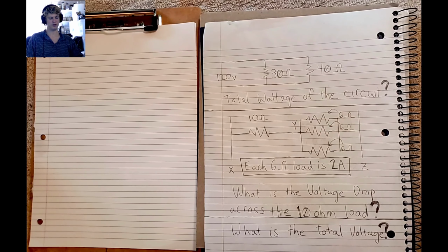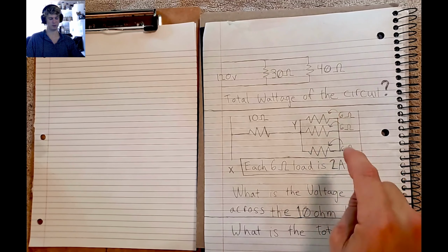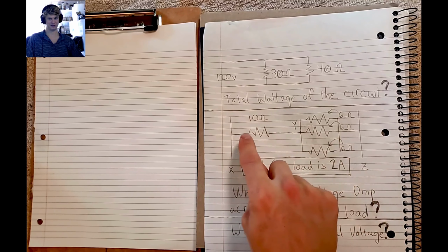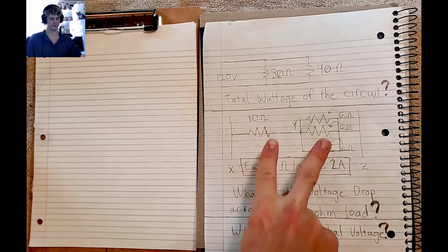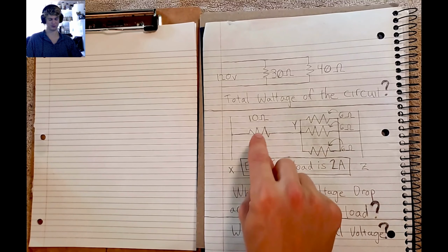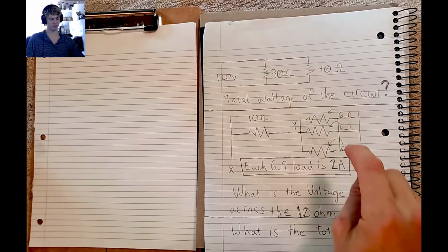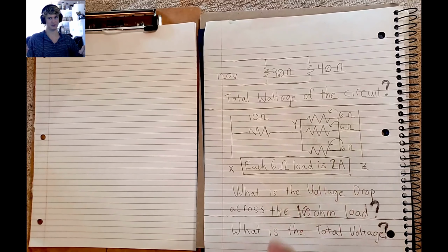Okay, so now we know if we have a total current of our 3 resistors wired in parallel, since that section is connected to this resistor that's wired in series, then we know that they're going to share the same current. So to figure out the current going through this resistor, all that we have to do is find out the total current for these 3 resistors wired in parallel, which we already have the current for each of them. Again, like I explained in my series versus parallel circuit video, when you have circuits that are wired in parallel, you're going to be adding the current together.